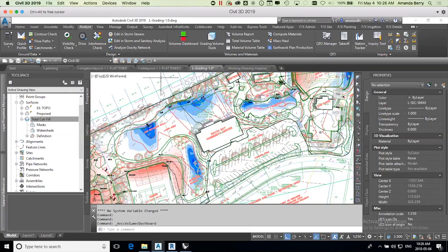I was able to then take that survey that he got after building it, plugged in those survey numbers in here, generated another surface, did a comparison, and found out he built the soccer field 1 foot too low. So it's really powerful being able to say, well, there's your 400 trucks worth of soil. No, you don't get an extra.